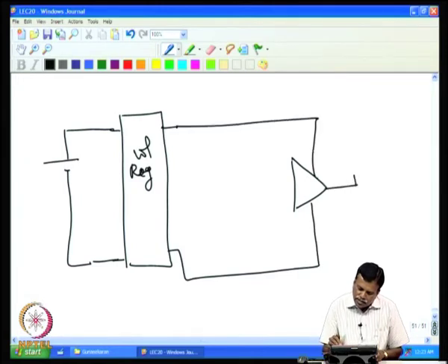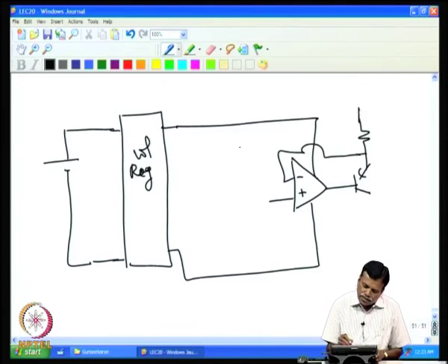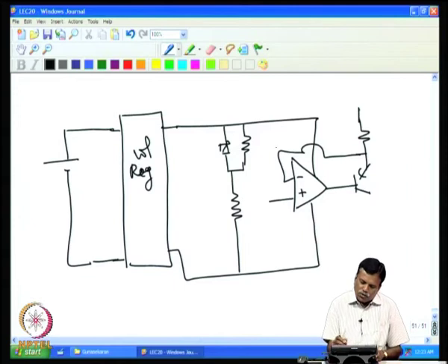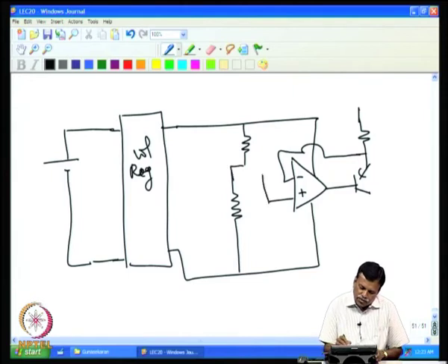Then we connect the current transmitter part, similar to what we had discussed. Then this regulated output only we connect to the potentiometer. Of course, to limit the voltage across that, we can have this zener. Even if the regulated voltage is there, the zener is not required, one can scale directly, even without the zener it works, there is no problem. So, one can have this directly connected here, and then one can have this potentiometer connected like this.